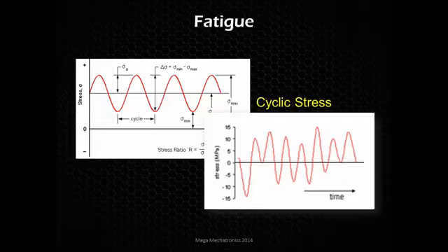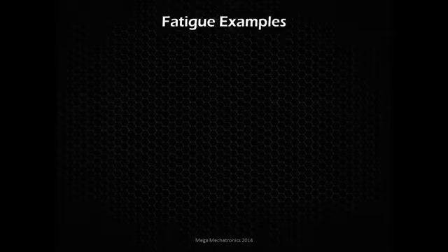And things like this are curveballs, you could say, where some parts may enter a certain harmonic frequency, a natural frequency, and the stress being applied to that part matches that natural frequency, and then things get really excited. Things get out of control beyond what the engineers have expected, or it just could be the nature of how that part is stressed. So some examples.